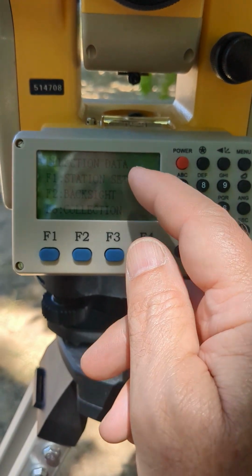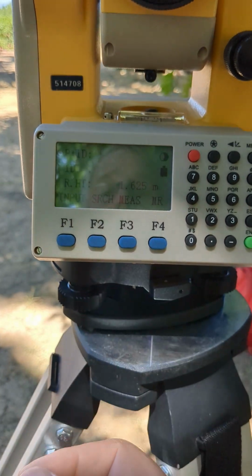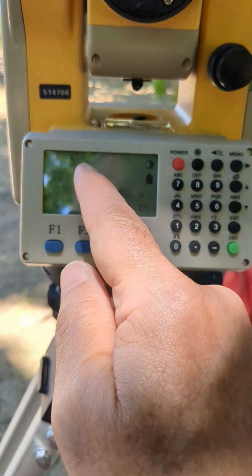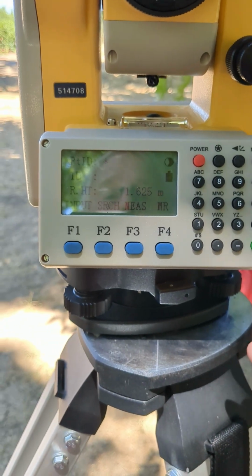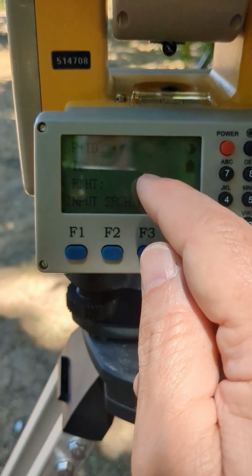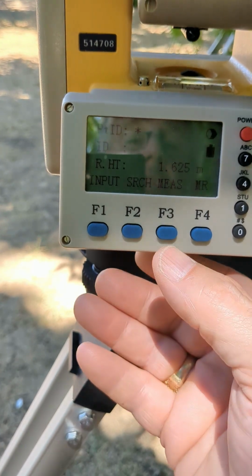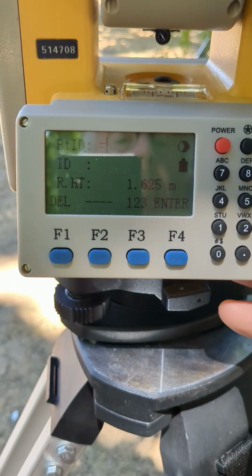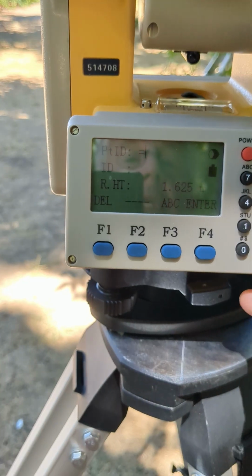I can now, so I did my station setup, I can now go to make a collection. I'm going to hit F3. F3, I want to measure a point. So I give it a name of a point. This is so when I download the data, I'm going to have names and things in my Excel spreadsheet. This point ID lets me maybe put some alphanumeric. I'm going to say input and call this point maybe alphanumeric ABC.